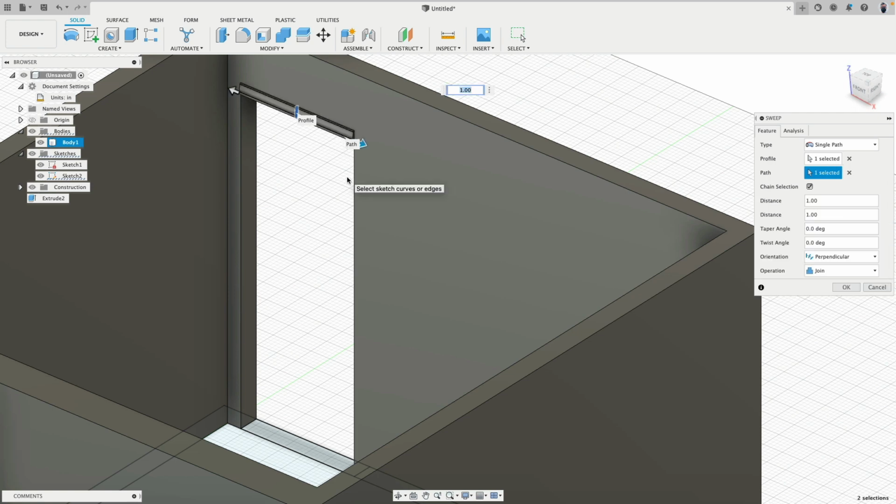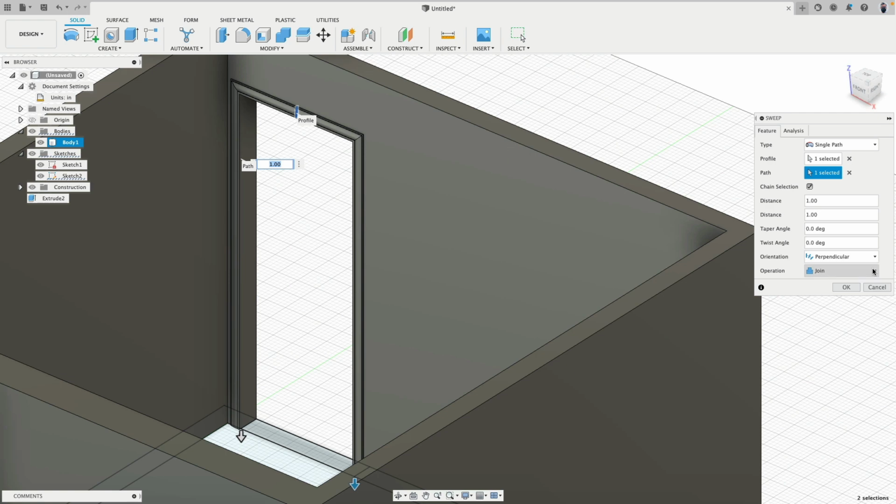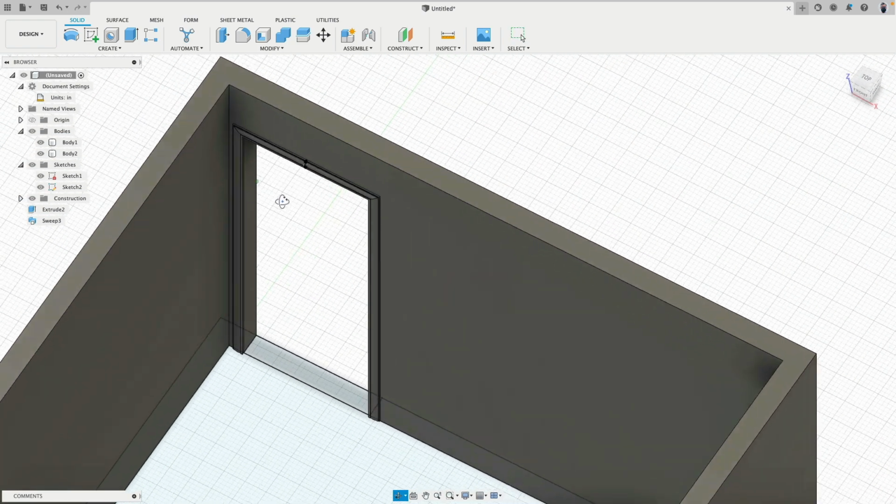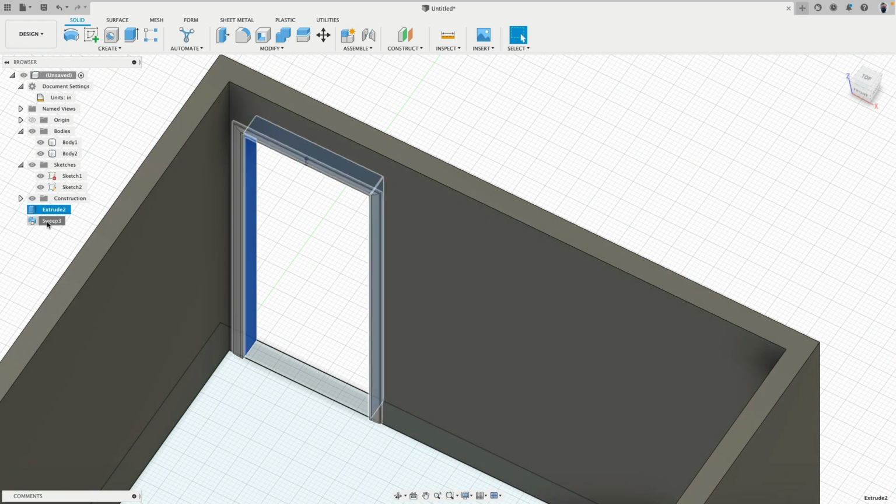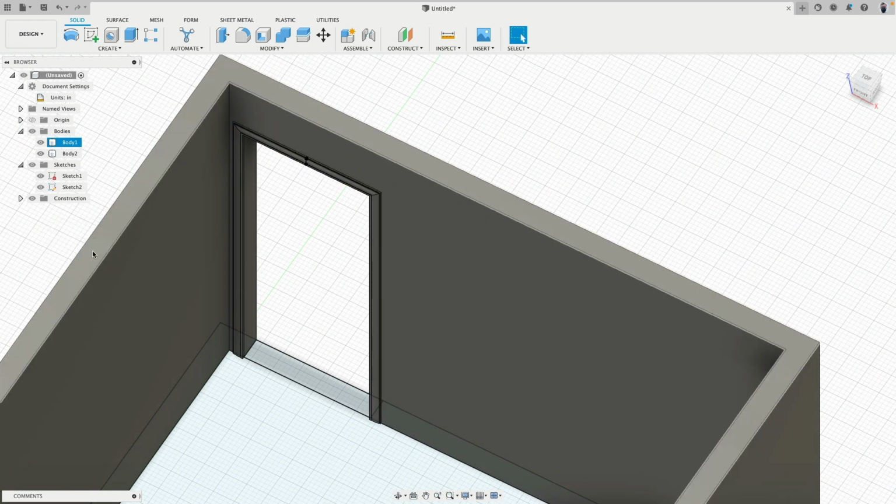And then on the Mac, I'm holding the command key. On a PC, I think it's a control key. Click and click. Do not join, really, as a new body. When I click new body, you will see here in a moment a new body when I click OK. There. The join command otherwise would have joined this together into one body, one group.